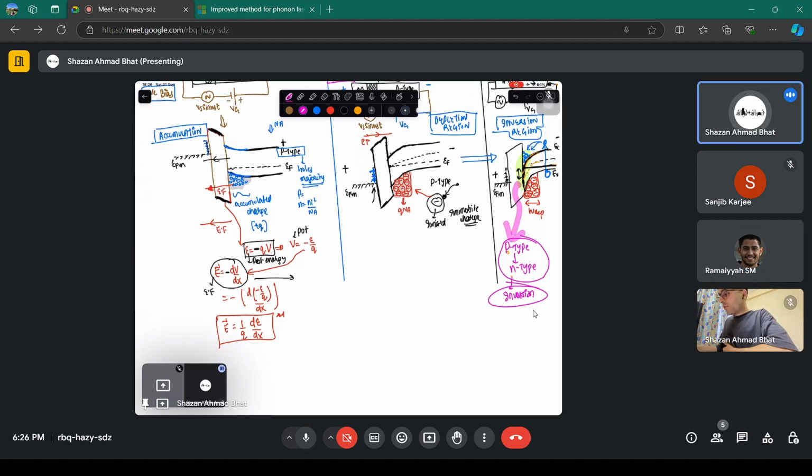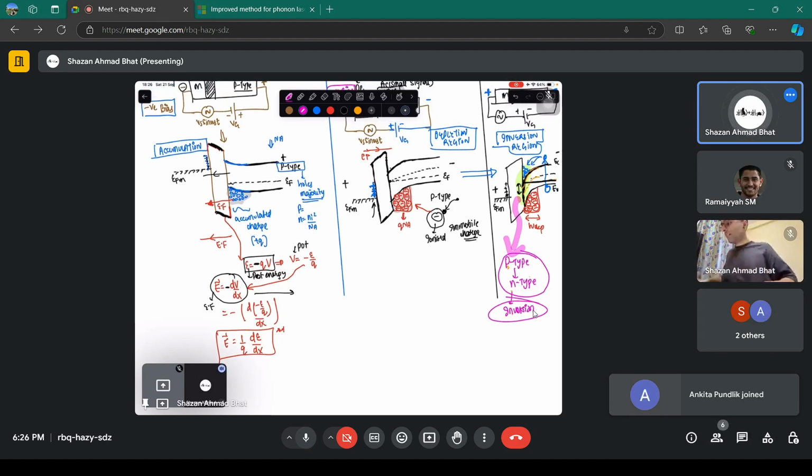Now there are electrons, there are depletion charges as well. So now we have to deal with it. Beyond that, this is it. We want the inversion to happen. Once the inversion happens, now we can play with these charges. That is what you will study in the next lecture in something called the MOSFET. When you go into the MOSFET, you will study how you control these charges, how you make them flow, how you turn it into ones and zeros, how you amplify the signal.